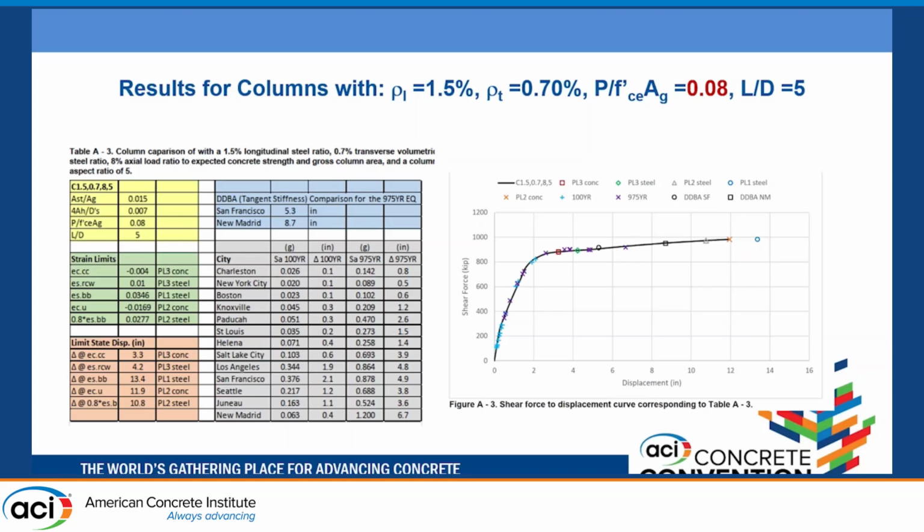PL3 for the concrete is the red box, just a little bit to the side, still fine for the lower level 100-year earthquake. This design was not iterated until we were right at some limit; we just picked a column, and that's the way we went through here. This is not unusual in bridge design. You don't always take everything out to the limit.